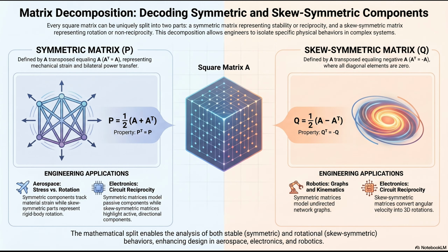But then the text introduces the skew symmetric component, Q, which represents the non-reciprocal behavior. The active components, yes. Right. It lists things like gyrators, circulators, and certain amplifier setups. And these components completely disrupt that bilateral flow. They take the electrical energy and force directional routing. Okay, so to stick with the traffic analogy, the skew-symmetric matrix represents the aggressive traffic controls. Yes. It's like the traffic cop, or the one-way street sign, that forces cars down a highly specific path and explicitly forbids them from flowing backwards.